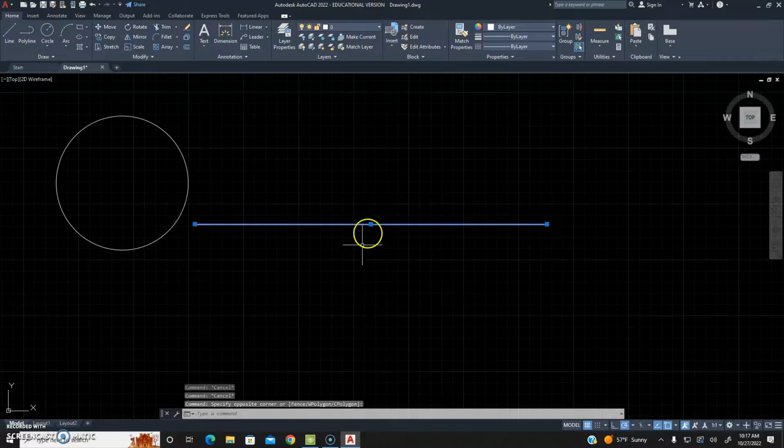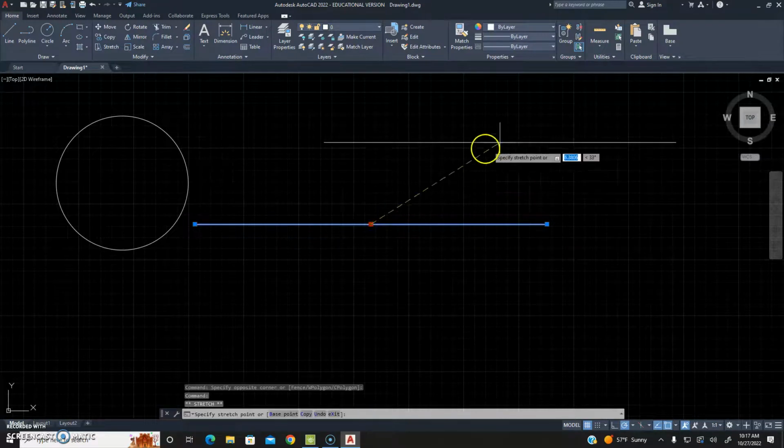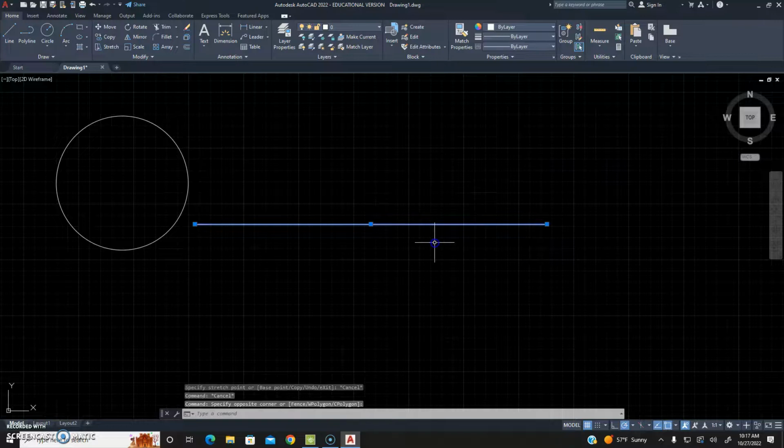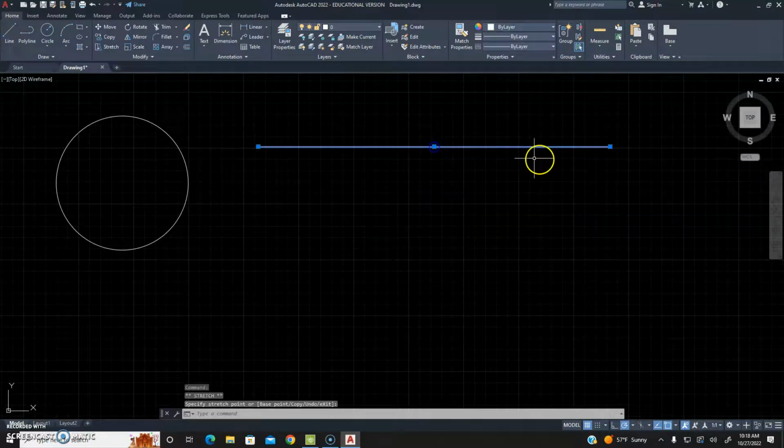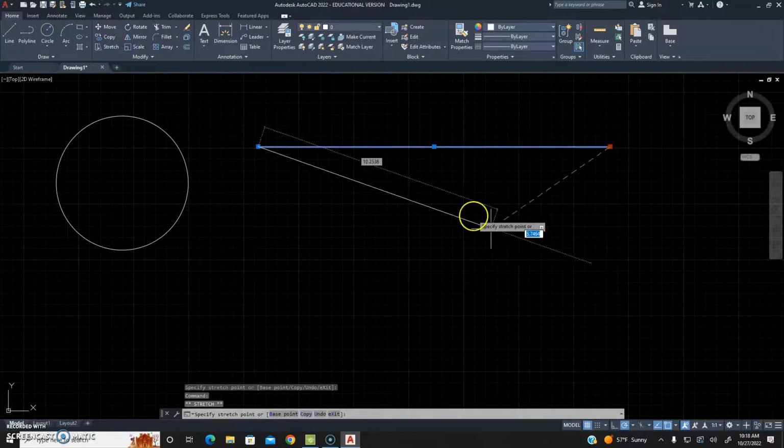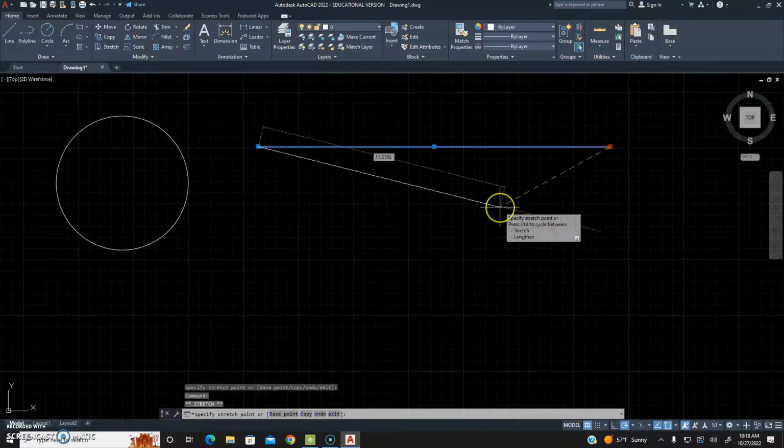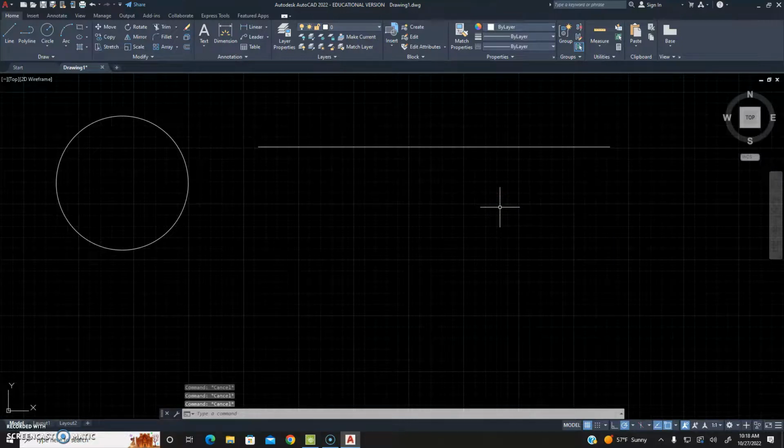For lines, it kind of works similar. If I want to move them around, I use the middle handle. Again, just sort of select them and then left click on the middle button, and then if I grab the ends, it'll stretch them and move them whatever way I need them to. I'm just going to hit escape. So that's center radius circle.